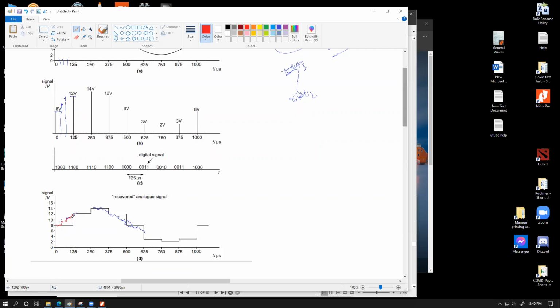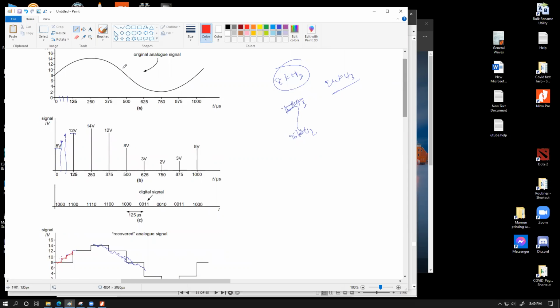So if we had a much higher sampling frequency, we could observe the original analog signal more often, and that would keep a bigger fraction of the data of the original analog signal, and that would have been better to create a signal more similar to the original analog signal. That basically means that a higher sampling frequency would make the recovered analog signal less grainy and look more like the original analog signal.